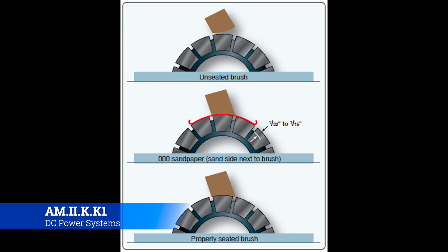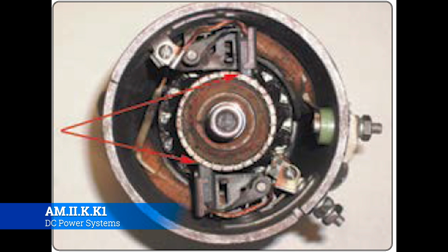DC generator. Okay, other parts and pieces of maintenance that you're going to be looking at whenever you're inspecting a DC generator: you're always going to be doing GVIs, a general visual inspection of different areas. You're looking for wear, you're looking for any sort of looseness that shouldn't happen. So you're going to grab the drive shaft, and if it starts moving all around, there's something not right there. There's going to be a bearing going out. And these things move, and they wear and tear, and they're subject to heat and dirt and things like that. So they will fail from time to time.